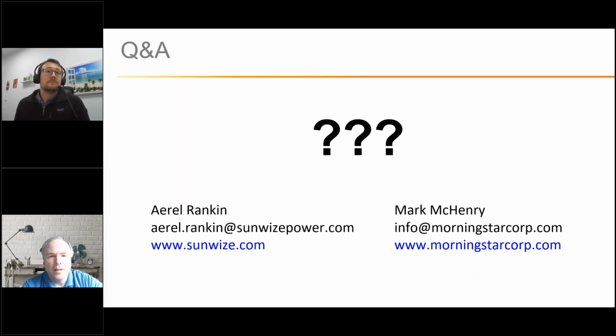All right, very good. I think I'll take this one. Mike's asking, is there any conformal coating on the controller PC boards operating in roadside salt-rich environments? So the answer to that would be yes. The Morningstar controllers have conformal coating and epoxy encapsulation. So yes, for that exact reason and other reasons, not only roadside salt, but other regions of the world where our controllers go. There's all types of dust and other debris and contaminants that we want to protect the PC boards from. So thanks for that question.